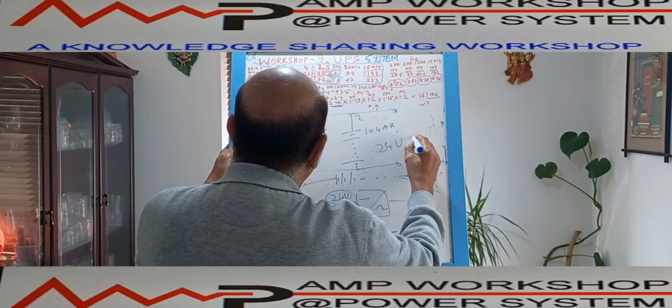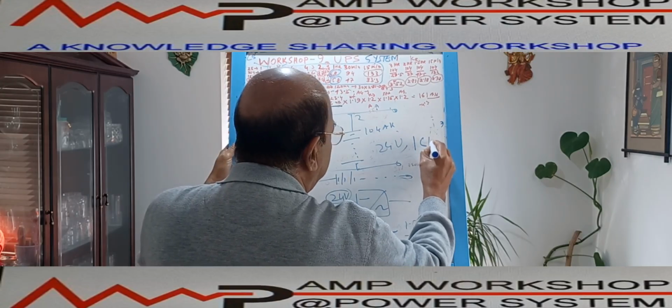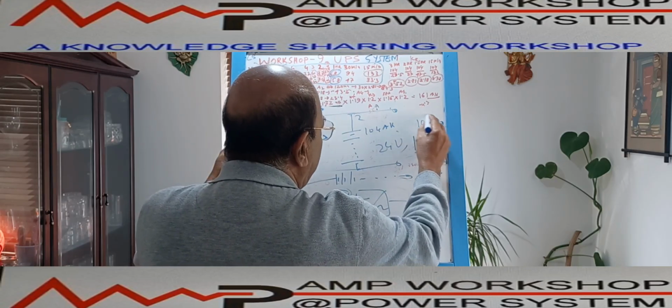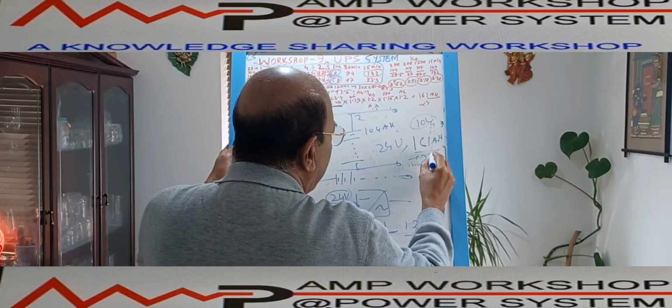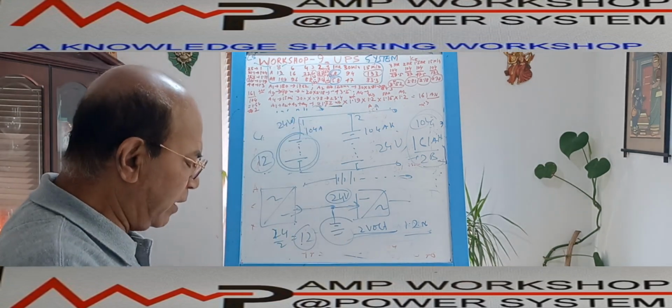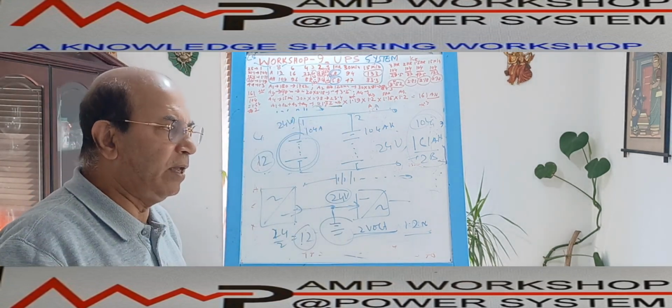How much ampere hour do we need? We need 161 ampere hour. As we have considered 104 ampere hour batteries, we need 2 banks of battery. That is our battery sizing. This is the way I need to calculate the battery sizing for the variable load.